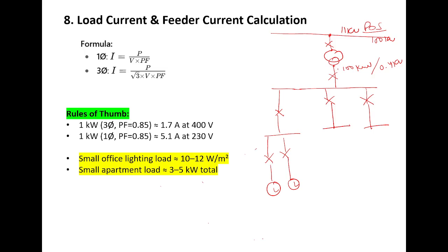So you will find in most cases the size of the cable at the primary side will be less as compared to the secondary side, because the current value will increase by the same factor as your voltage is decreased. Because you already know power is directly proportional to VI. As this voltage is decreasing, by the same factor current is increasing, because P is constant.